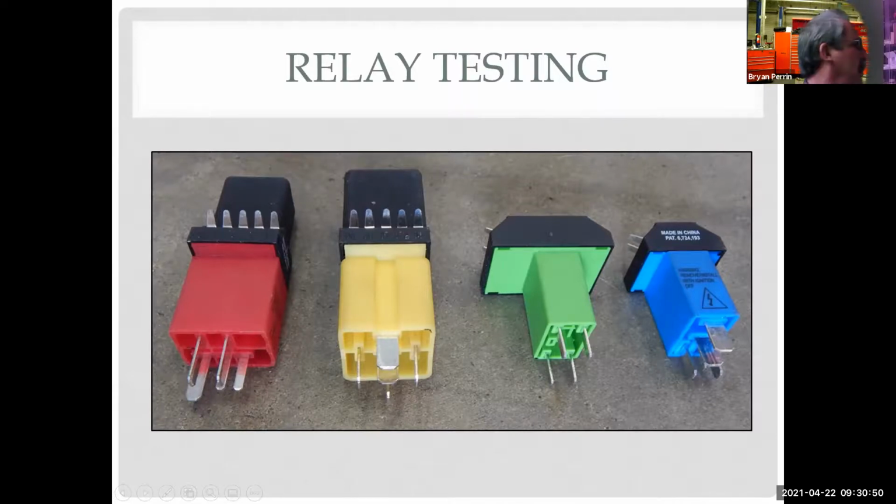Then I can do all my testing with my preferred tool, which happens to be a power probe, right here. All I've got to do is figure out which relay is for the circuit that's not working, take the relay out, plug this in, connect my power probe, and then I can test the whole circuit based on the wiring schematic and watch the relay that's installed in the top work and see what's going on with the circuit. When we get into cooling systems, I do a demo on this and you'll get to see it. I have a video lab that we do.